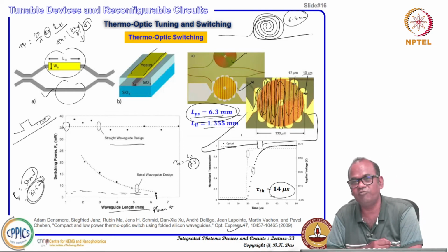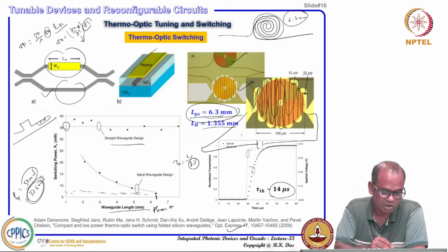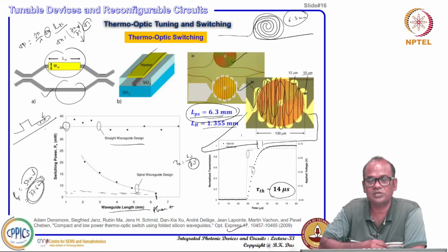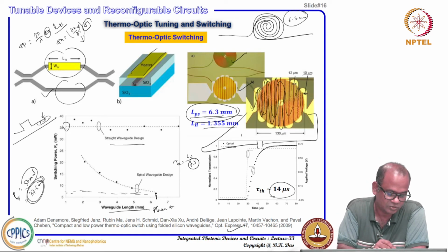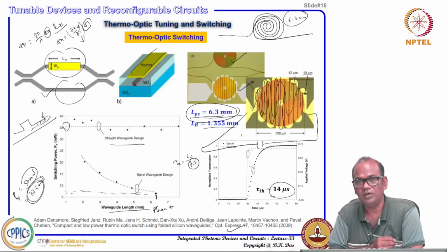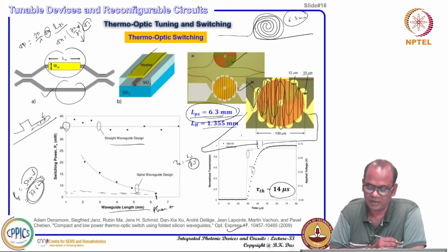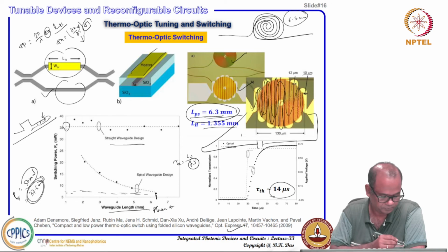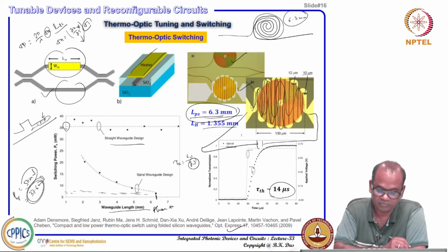It is silicon, and when you fabricate the waveguide, it is intrinsic. Now if you dope p type or n type, then it will be a conductor. So if you send current through that, Joule heating energy will be conducted, the temperature of the waveguide will increase, and in turn you can get a higher refractive index change. So that is another type.